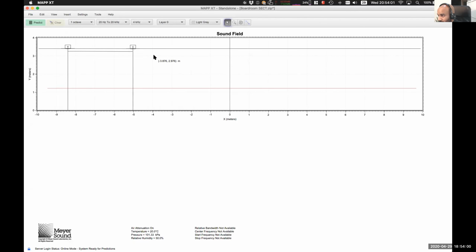placement of these loudspeakers. Now, to copy these on next, I can just select the loudspeaker, select the line, and copy them together. Again, Command C and Command V. As you see, it's copying with the line. So now I can quickly go and place them like that. And it becomes that much easier to quickly place the loudspeakers at the even spacing that you need to do.